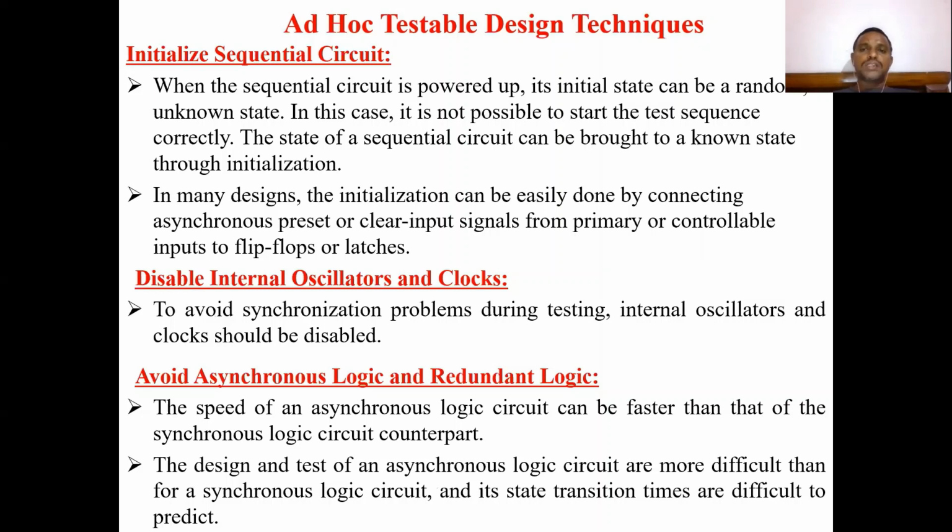We don't know the initial state of those flip-flops or that sequential circuit. So what we do is initialize the state with a known value. After that, we apply the test vectors so that it is very easy to observe the outputs for the given test vectors.